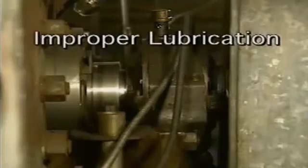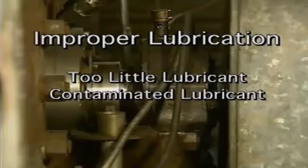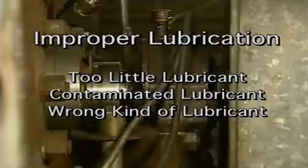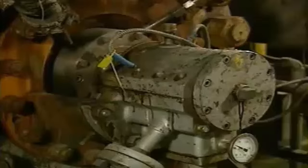Another cause of sliding surface bearing failure is improper lubrication. Improper lubrication refers to three different situations: too little lubricant, contaminated lubricant, and the wrong kind of lubricant. Too little lubricant can prevent the formation of the lubricant film that's required between the bearing and the shaft.